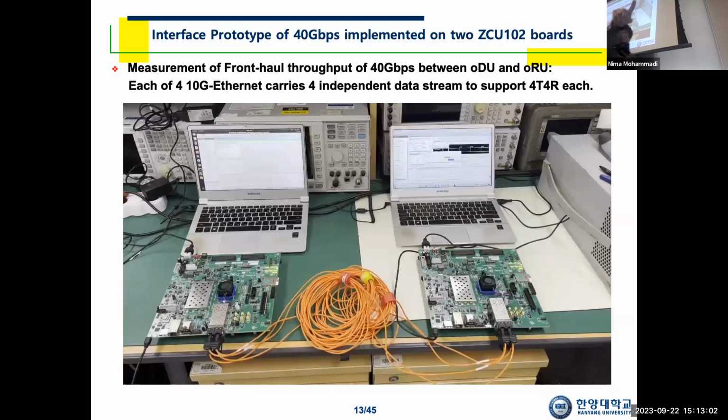Okay? So at the transmitter, I perform the framing procedure. So OFDM sample values are mapped into ORAN packet first, appending eCPRI header, it becomes eCPRI packet, then appending physical layer Ethernet header, it becomes physical layer packet, then transmitted via 10 gig Ethernet port.